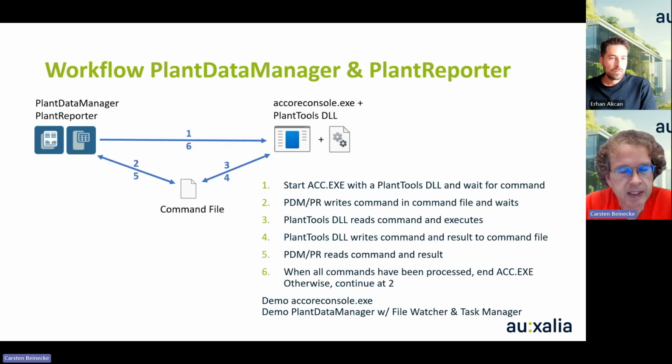Okay, so how do Plant Data Manager and Plant Reporter work with collaboration projects? I will demonstrate that, so I will be a little bit shorter here. If you start Plant Data Manager or Plant Reporter and want to open a collaboration project, Plant Data Manager starts the so-called AC Core Console. This is essentially an AutoCAD without a user interface. It's just a command line. Typically, you don't start that, but Plant Data Manager can start it in the background.